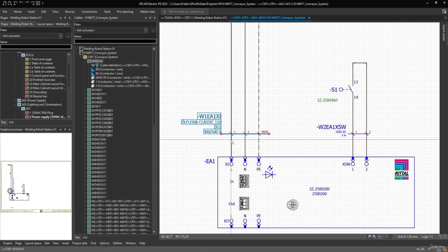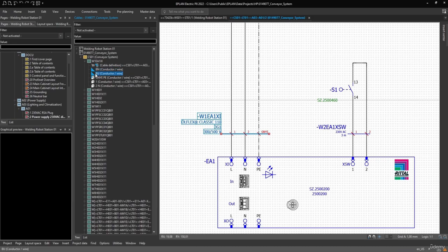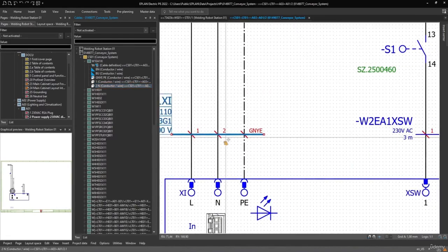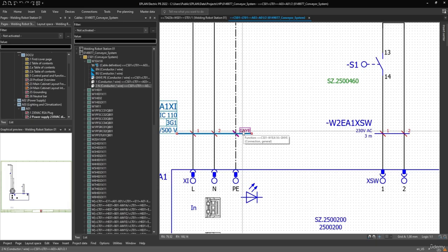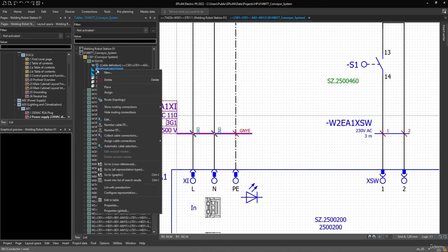So as you can see, this specific cable actually uses a blue core, and it also uses a brown core. It doesn't use a 1 and a 2. So currently it's written 1 and 2, and it's written the green and yellow. The green and yellow is the only one that's correct. You can see it as a cube and a triangle. That's correct. But these two, the 1 and 2, they're actually incorrect. So it's not supposed to be 1 and 2 there. So you can easily just right click on that one and you can assign it.